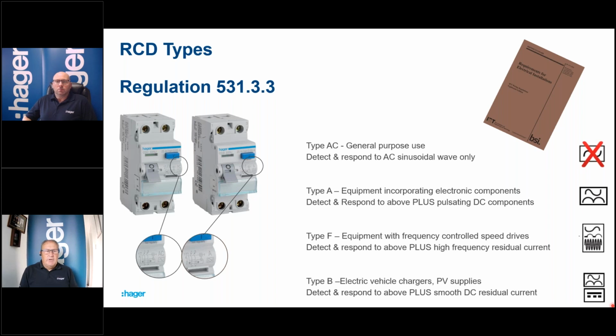Be a little bit careful when you're maybe buying just an RCCB on its own from a wholesaler, or from other sources where you might get some of these electrical products from, because obviously some old stock could exist. It would be really old stock now, of course, but it's actually quite difficult to tell. The picture on the left there, they actually look quite similar, don't they? Or they actually look bang on the same almost.